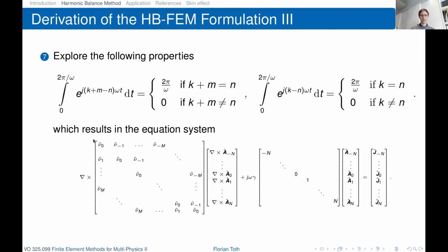So you have the curl of a matrix expression. So this is actually the product of the two Fourier series that we had. And you can write this resulting sum in matrix form. And on the right-hand side, you come up with the lines for the different harmonics. And similarly here for the mass term we had, so this was the time derivative of the magnetic vector potential.